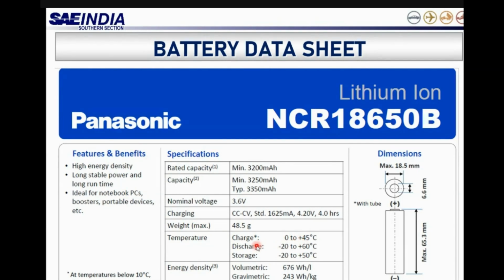So when you have a sub-zero temperature and you develop a vehicle, that's when you apply engineering to first condition your battery pack so the cells are within the temperature range provided by the supplier. Likewise for discharging. You cannot exceed this limit, and that's how the thermal management system has to be defined.